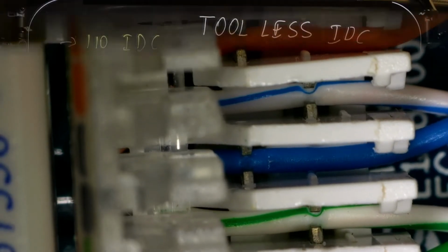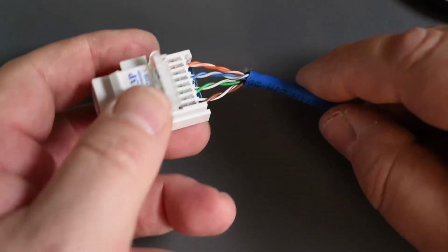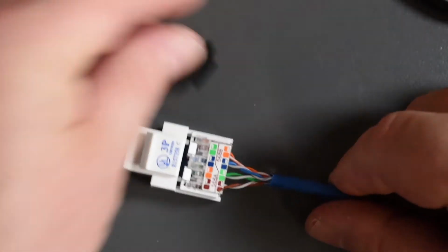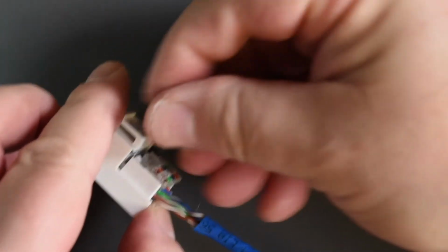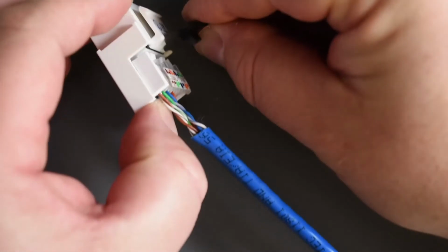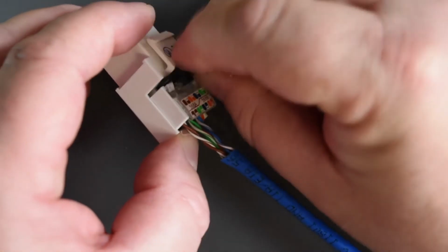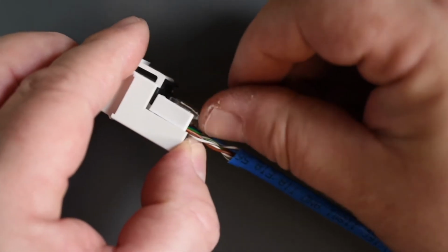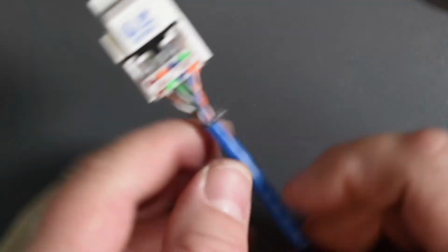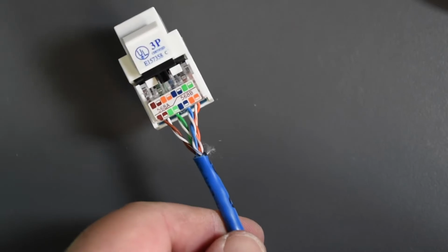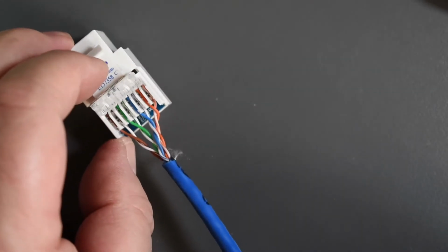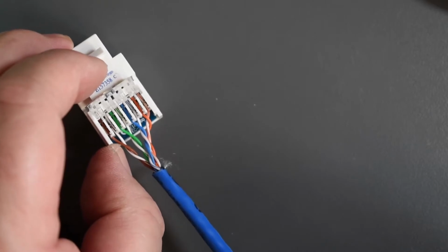Right. And then the last thing we're going to do is close the hinge for the last time, and reapply the clip. I'm just going to get that clip here and put that in and push it in. Okay. Now this hinge is not going to open. So this is how you terminate the Cat5e. Notice the twist goes right to the end. Right? Oh, I can't open it. Twist goes right to as far as possible.